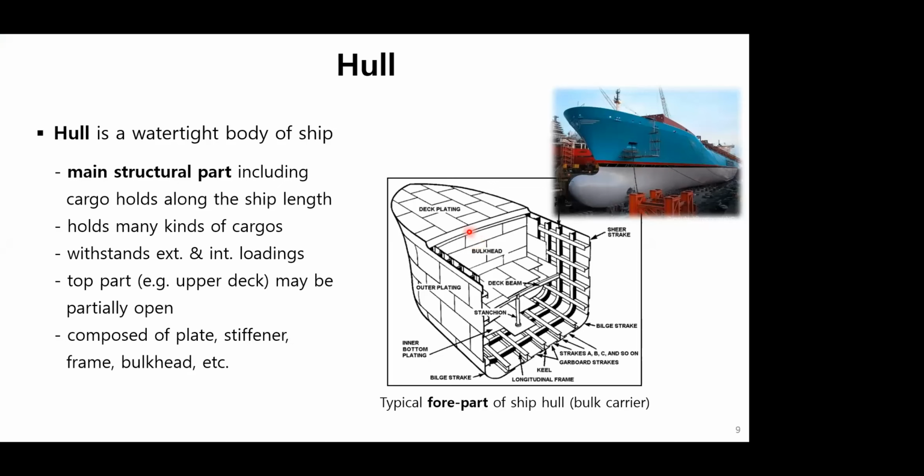I'd like to talk more about hull. Hull may be said to be the watertight body of a ship. That is the main structure part, including cargo holds along the whole ship length. Hull is supposed to hold many kinds of cargoes, also withstand external and internal loadings. Top part of the hull, so-called upper deck, may be partially open in order to manage cargoes.